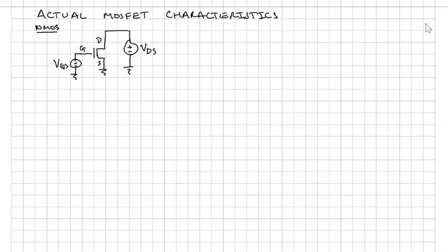And we said in triode mode, this gives us basically a linear characteristic when we look at the drain current versus drain voltage. It looks like a resistor. Again, this is all sort of a review of what we did in the last one. And we have this other piece of the pie down here on the I = 0 axis where we're in cutoff. If VGS is less than VT, that's cutoff, no current flows.